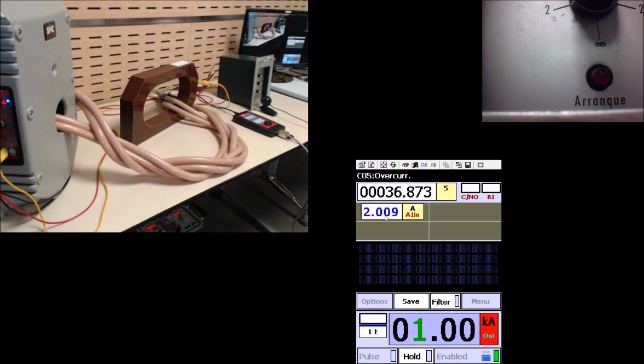All right, so I can even modify dynamically the output. Now I'm going to 0, but I am going back to 1. I can select a different digit for a fine adjustment. You see, I think that you have seen the pickup light coming on at the top right corner of the screen, and now we have a trip time. But this is not a valid trip time because I have been injecting for a very long time with a non-tripping amount of current.